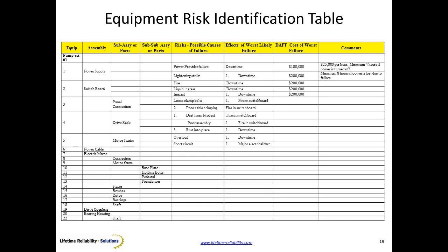And on we go. So what is the effect of that event if it happens? Worst case, if that bearing in this motor fails, what's the effect on the motor, on the process, and of course on the company? So in the end, I want to work out what's the defect and failure total cost. What will this company lose globally if this happens? Because that's serious money. That's the money I've got to talk to managers with.